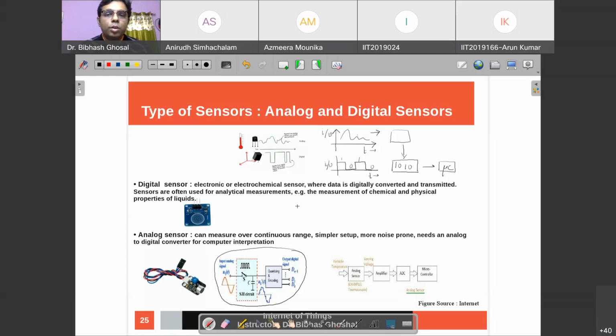So what we do is we convert this into a discrete signal, then we round it off, and then we finally encode. The first step is that instead of taking all values, we take only certain values. So if we call this the analog, this is the one that is actually generated. This is called discrete. How do you discretize that? Well, you don't take all values, you take only certain values. The way to go from here to here is called sampling, that you take samples, right? Only certain values.